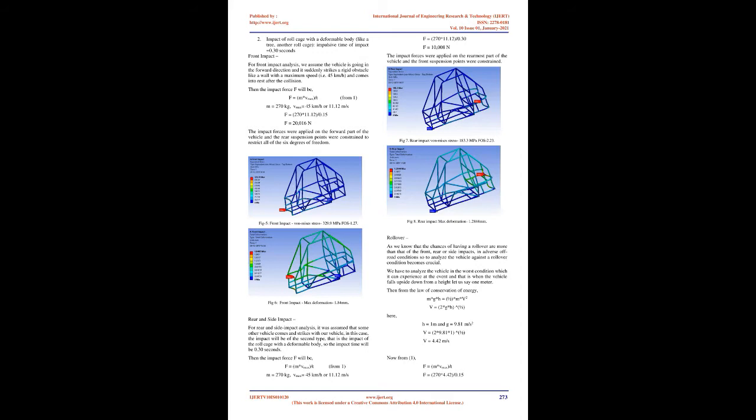We can see AISI 4130 provides good strength, but at the same time it is costlier than AISI 1018 and has poor weldability. Also after considering the fabrication constraints like available welding method, we used SMAW, availability of the material in local market, and total cost, we selected AISI 1018 steel as our primary and secondary material because it is cheap, easily available, can be welded by SMAW, and it also provides sufficient bending strength and bending stiffness to overcome the constraints for primary material as